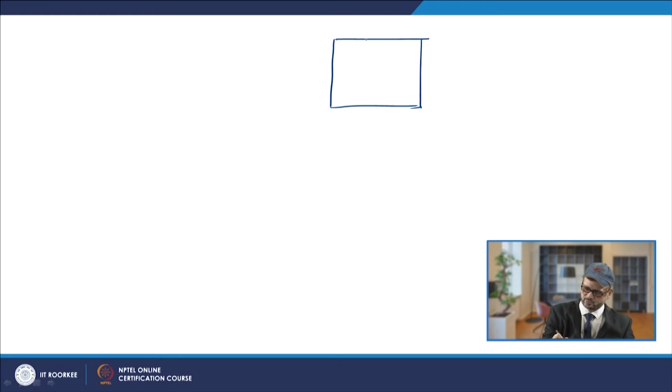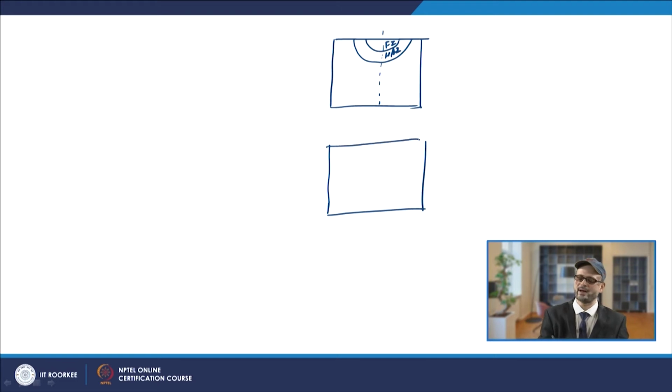You can understand this by referring to a schematic figure. Your fusion zone earlier was like this, and your heat affected zone can be shown this way. You have some temperature in those zones too. Now, if you preheat to maybe 250 degrees centigrade, it was seen that this zone got widened.